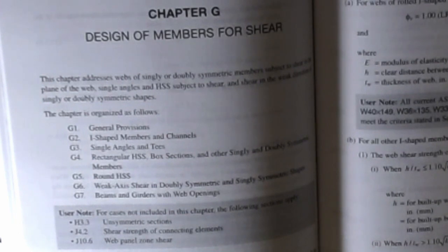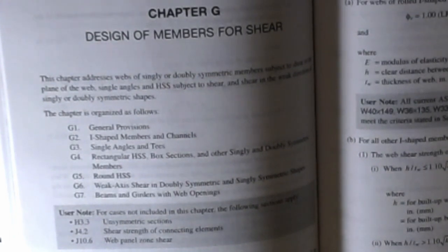The governing specifications are located in Chapter G. For once, the lettering makes sense to me. I know most of the time you think, oh, shear, that's V, but G makes sense to me because if you remember back in mechanics of materials, the elastic shear modulus, the typical constant that relates the shear stress to the shear strain, was the letter G. So that's one way that I can always remember this. It's not like some of those other scenarios, like tension members located in Chapter D, or connections, which are often located in Chapter J. There's no rhyme or reason to the order, at least not that I've been made aware of.